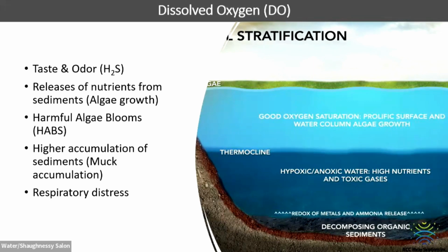As soon as you drop to about 4 milligrams per liter, and this is a generalization, it varies depending on pH and temperature, but as soon as you hit about 4 milligrams per liter of oxygen at the sediment water interface, we start to see a redox of chemicals. The first one that happens is manganese. So manganese is the one that starts to dump out of your sediments at 4 milligrams. Some phosphorus will come out at that point as well, because manganese is often bound to phosphorus in the presence of oxygen. You take away that oxygen, that bond starts to break. When you hit 2 milligrams per liter at the sediment water interface, then we start to see phosphorus and iron come out, because there's another bond there that is oxygen dependent, and they come out in large quantities.